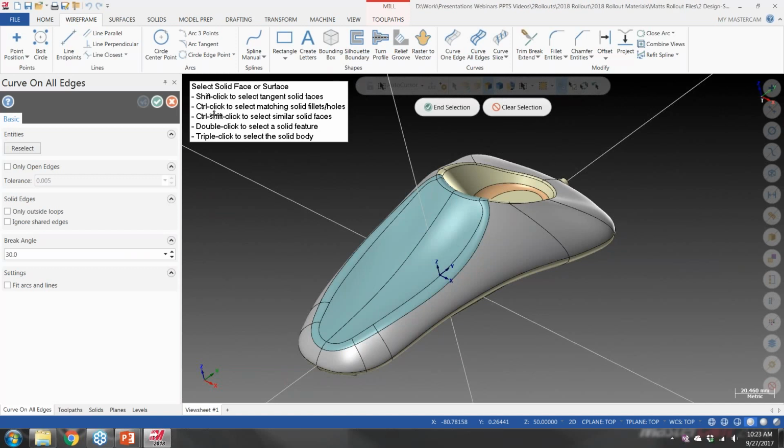So these are the enhanced selection tools I was talking about. You have Shift-click for tangent faces, Control-click for matching fillets, and double-click to select a feature. If you have bosses or additional features on a part, it'll select all that are like that. And now triple-click is to select the entire body.